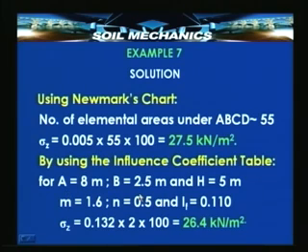You can see here that these dimensions are such that we will get m and n values corresponding to these, which will lie well within the influence coefficient table. So, we can also calculate the vertical stress here using the influence coefficient table. If we were to use that, then we need the dimensions a, b and the non-dimensional values of m and n. We find here a is 8 meters, b is 2.5 meters.